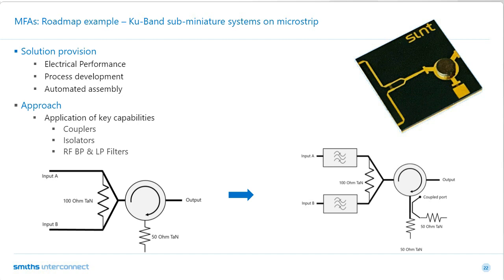So what you're looking at there is actually an isolator, and because we can now put our own circuit on that piece of ferrite, we no longer have to procure the individual termination. It's part of the circuit. And what you have here is not just a standalone microwave integrated circuit isolator, but it's combined with a Wilkinson power divider.